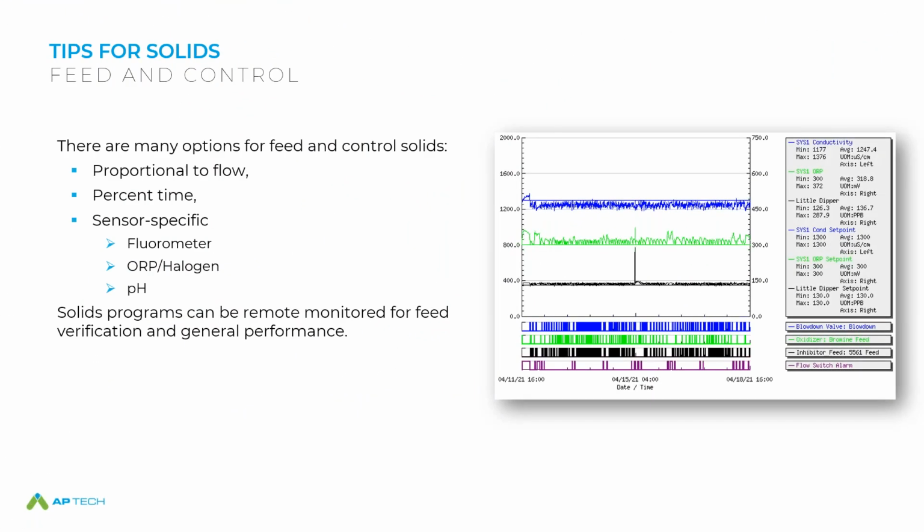And then lastly, this will segue into Tom's part of the presentation, but I did want to touch on this: don't think of having to do anything really functionally different with a solid program than a liquid program. You're still going to do proportional feed to flow, whether it's makeup or blowdown. You're still going to consider percent time. You're still going to do slug dosing on a 28-day biocide timer.